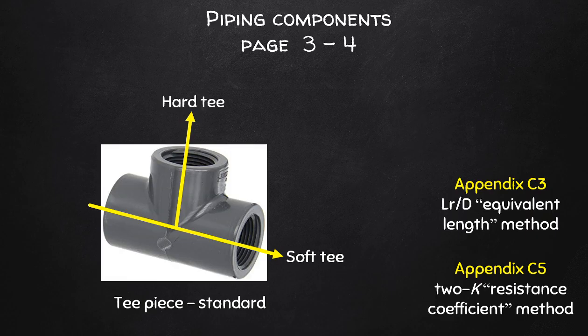T's are made up of three joineries, where one pathway is referred to as the soft T, since it causes the least resistance to flow because momentum is in the same direction always, while the hard T requires a hard change in momentum from a Y direction maybe to a Z direction or an X direction, and thereby it also is associated with higher resistance. How fluids flow through these T's must always be considered very carefully, because I'm going to try and trick you into applying this knowledge incorrectly. And in so doing, I help you to learn and understand.